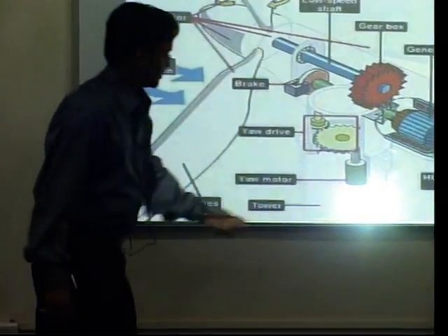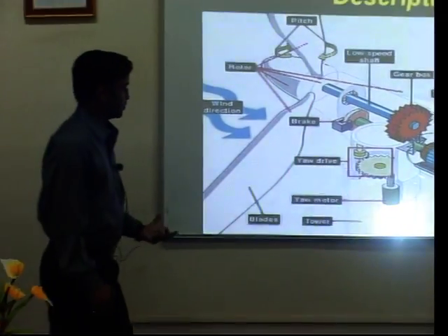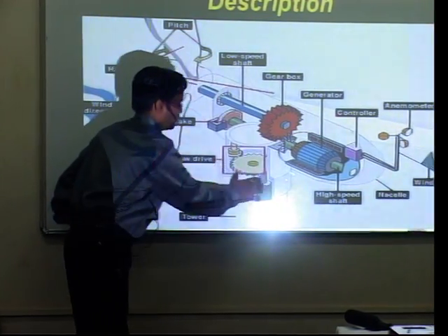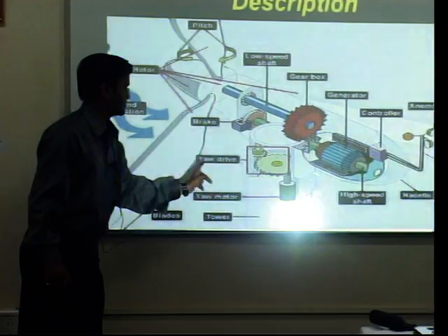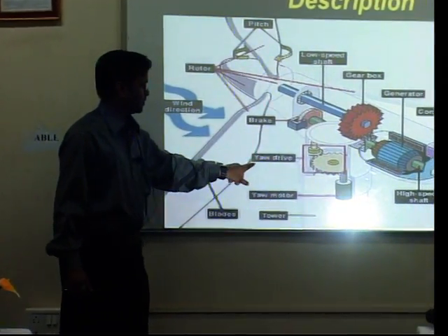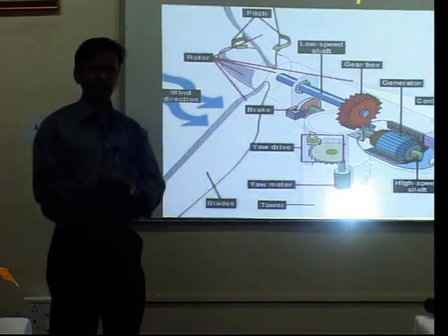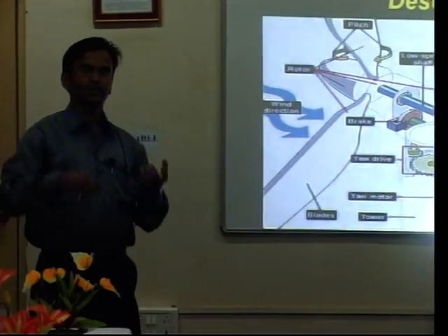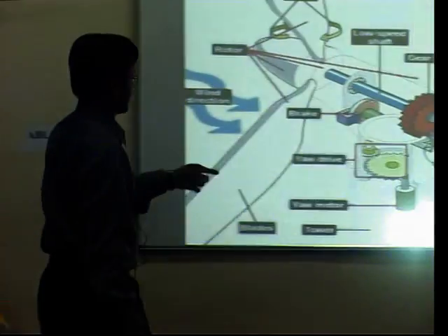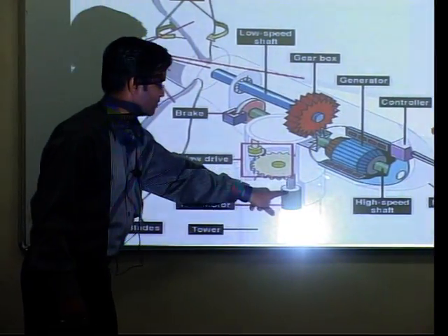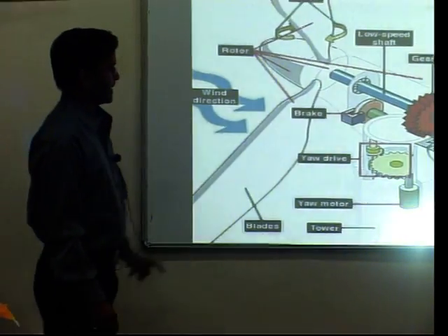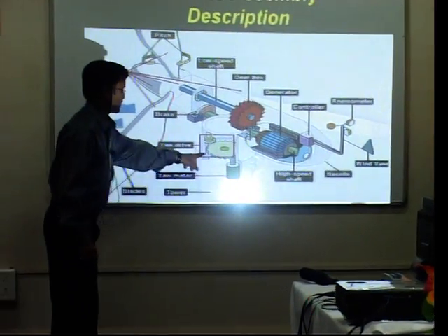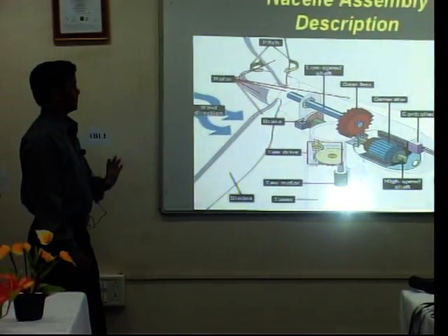And on this tower, the yaw mechanism or yaw drive is one of the important elements in this system. The yaw driving mechanism consists of a gear on which the pinion is fixed, and this is driven by the motor. Then this whole assembly is fixed on this yaw drive mechanism. This is a brief introduction.